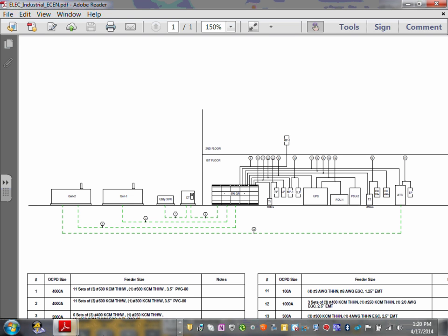You guys are engineers, so the first question you ask yourself is, where should I put my panels, right? Without getting into details, you're going to put your panels as close to your loads as you can. But we don't have a whole lot of control over it. Sometimes we get close. That's a discussion we have when we design the building, where we're going to locate our electrical panels so we can minimize the voltage drop. Voltage drop is a big issue when you design any commercial or industrial building.